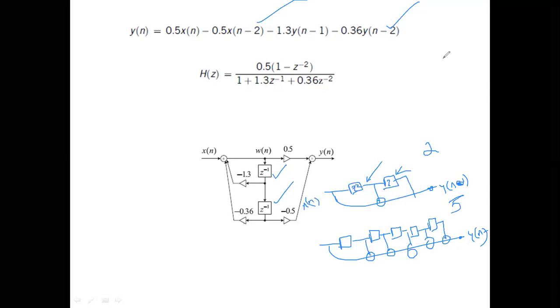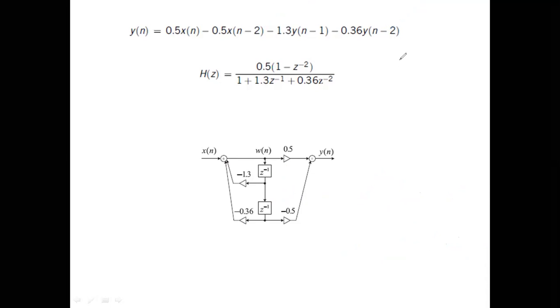So higher order filters are costlier. A filter of order 10 needs 10 D flip-flops, and a filter of order 20 needs 20 D flip-flops. Higher order filters are ideal and much better, but they are much costlier due to more D flip-flops, and much slower due to a large delay between when input is given and when the first valid output is required.